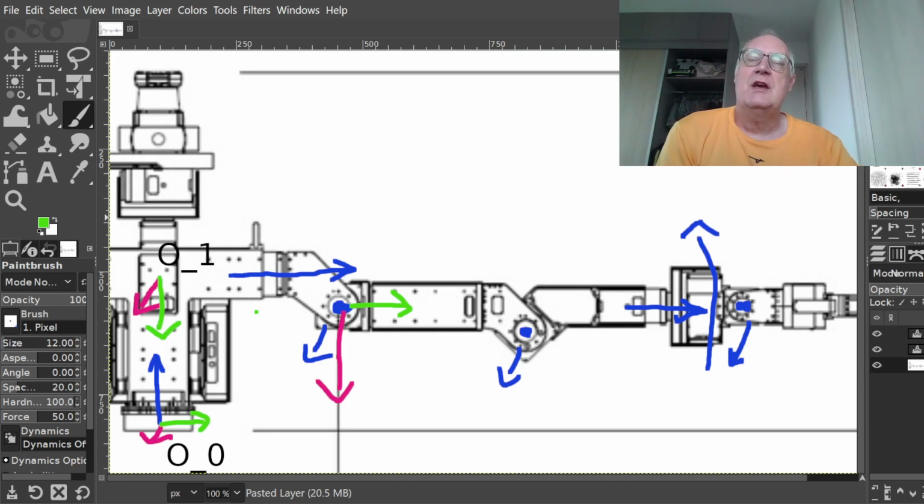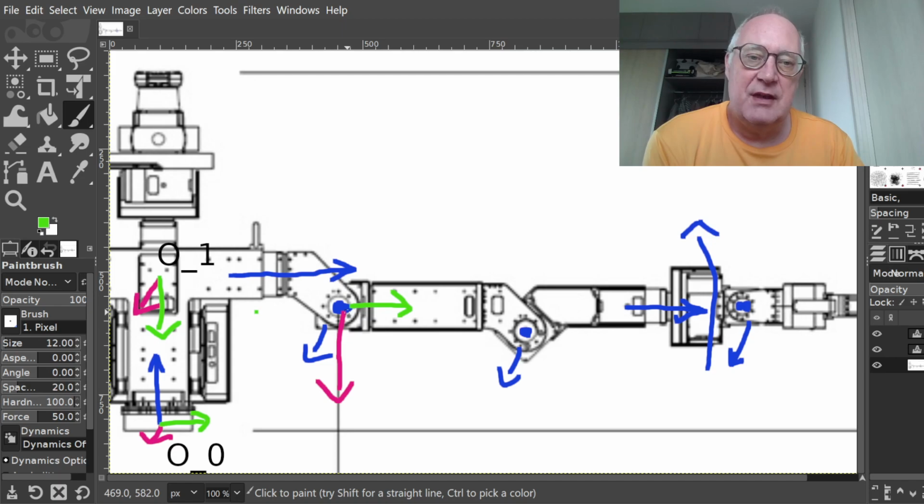Then we can choose xi anywhere we want. And the common way to do that is to align xi so that our displacement d becomes 0. Also, the z-axes are aligned with each other, so alpha i will be 0.